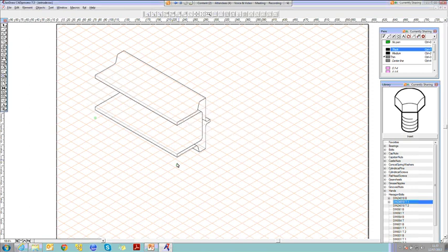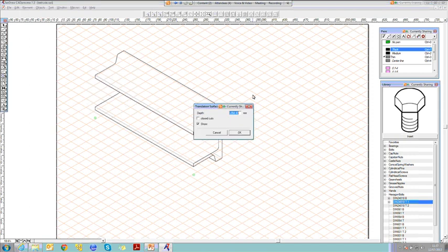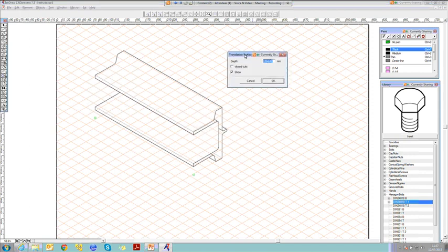And when I'm finished and I've got the length that I want, I also have an option to close the cut. You can see by ticking the close cut option what that's doing here. I could close the cut off, say OK, and then I've generated my projection nice and quick, and that's then generated in my drawing for me to reference, to add dimensions to, to work with, to add colour on. So all of that's available there.